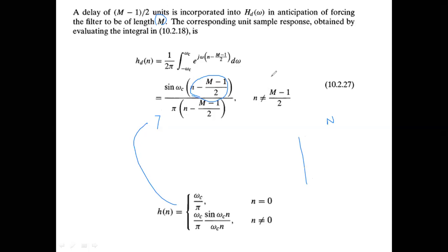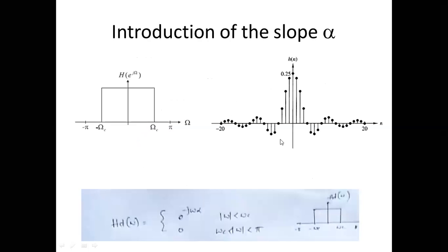Remember linear phase. Let me remind you that linear phase filters are those which are symmetrical about the midpoint. Now that you shifted it, is it still symmetrical? Yes, of course, it is still symmetrical. Symmetrical not about the y-axis, remember, but about the midpoint. There is some midpoint here also. So this is still symmetrical, but now there is phase introduced.